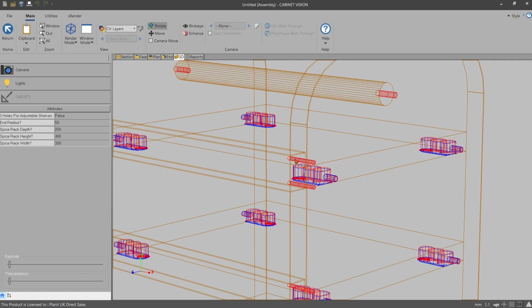So it's not just cabinetry. It's also machining that can be classed as parametric. We can add attributes to the positions and also the depths. I've actually got attributes on this drilling here to always be the material thickness. If that material thickness changed to 22, that bore in there would extend through the part. So it's clever things like that we're going to go through, which will hopefully put some more value in the software for you if you can do some more complicated things.